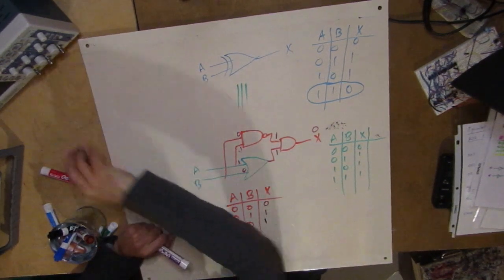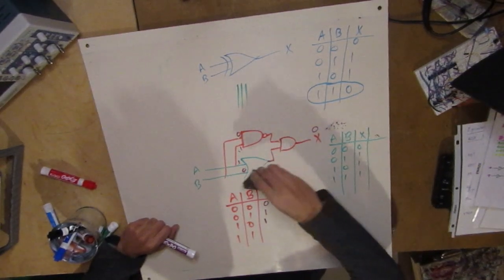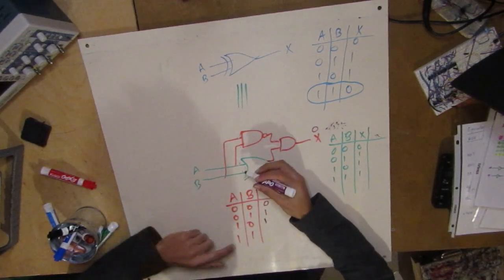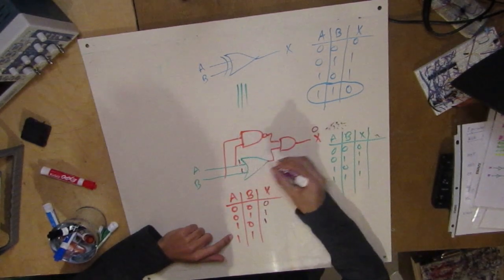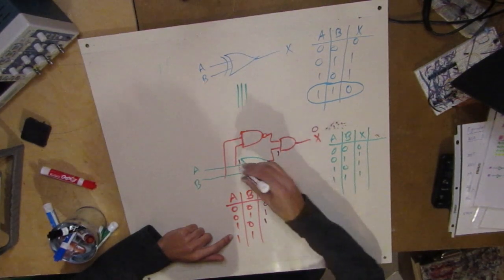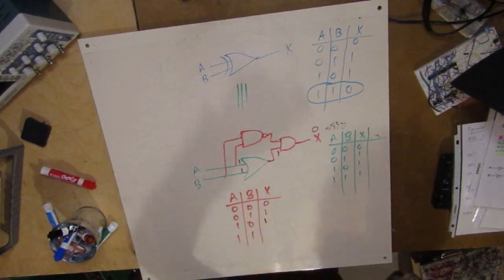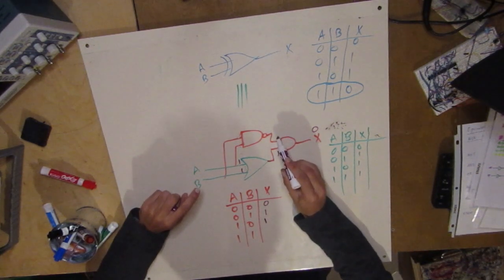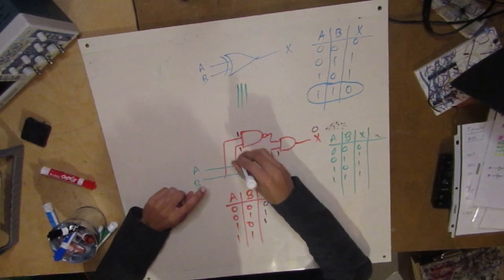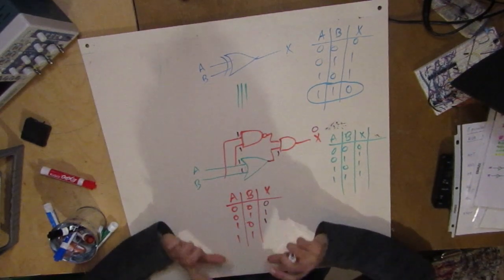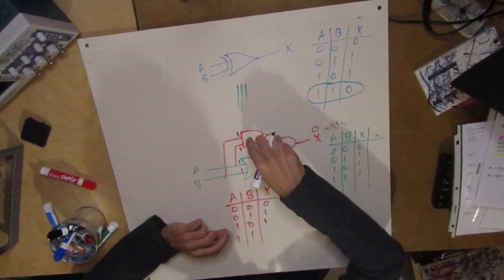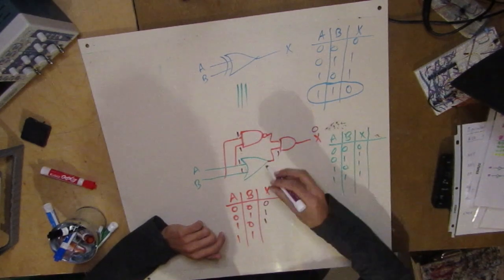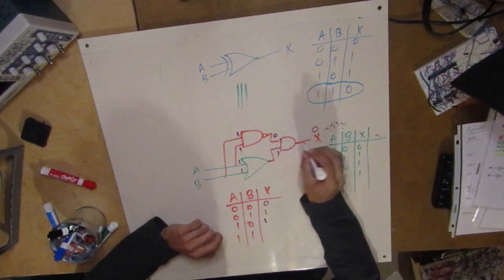Okay. Now let's do the final entry, where A is a 1 and B is a 1. So we put a 1, 1 here. At least one of them is going to be on, so we automatically know that there's a 1 coming in here. Now, the only way is to see if this is a 0. This has to be a 0 on the output. So we put a 1 here and a 1 here. Now this is an OR gate that's treating 1s as 0s. So this is technically an OR gate that's seeing 0s only because both of the inputs are 1. Okay, so this does not follow OR logic. So you get a 0 there.